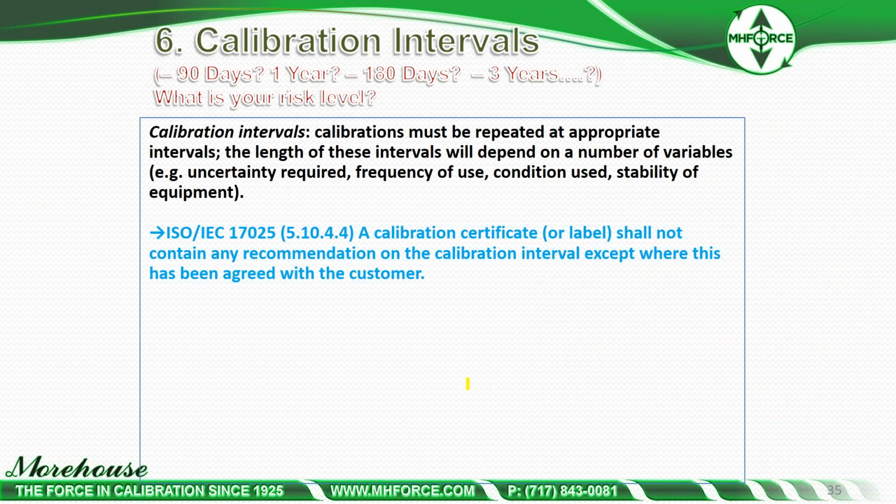Calibration must be repeated at the appropriate intervals. The length of these intervals will depend on the number of variables, uncertainty required, frequency of use, condition used, stability of equipment, all these things.